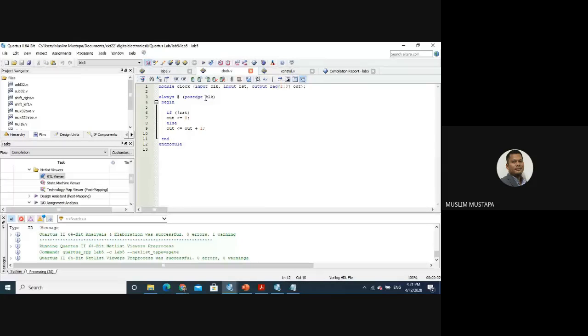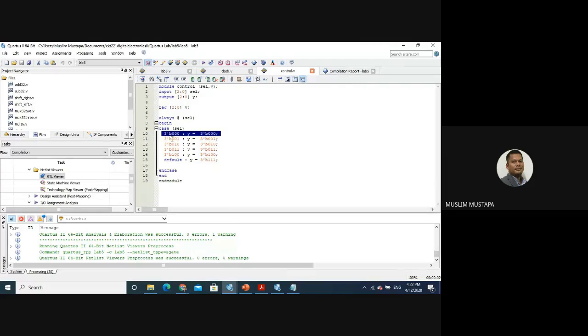On the positive edge, you need to add another counter that counts until 10. I've covered it in the lecture, how you can do that part. So you count 10 clock cycles, then you increase the output. Then another 10 clock cycles, then you increase it again. So each state will have 10 clock cycles. You can do this if you need more than 10 cycles, for example if you have a washing machine or whatsoever. That's how you can manipulate it.